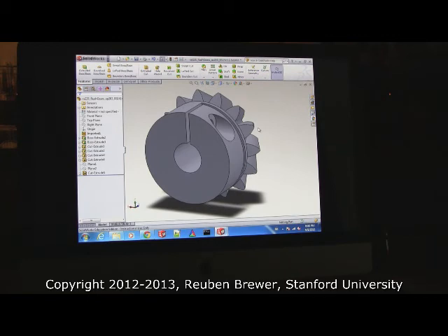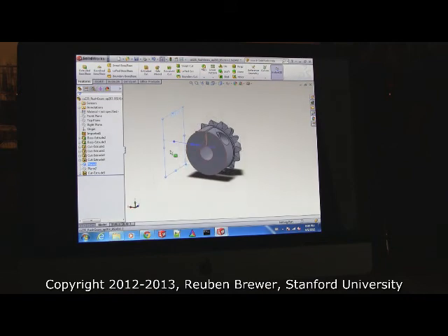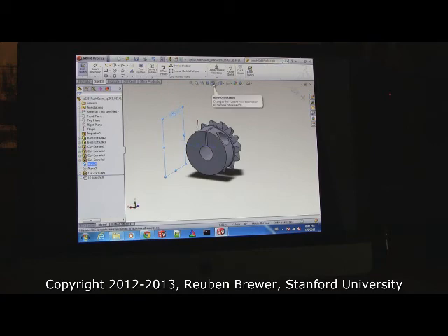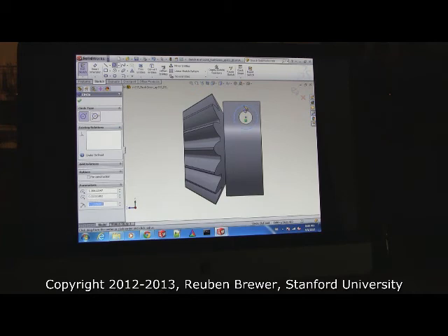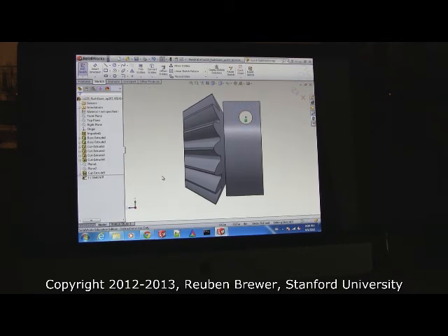Okay, hit the little check mark. Okay, this next one is fun. I think you actually really will like this. Select the other plane beneath the other hole. See this one? It's far away from the hole we just made. Select that one and do extruded cut. Now do the normal view. Okay. Now take a circle and center it here on that hole and make it about that size. And don't click; do for construction. This is reference only. Okay. Now hit escape. Now I'm going to wait and make sure everyone has this before I go ahead, because the next part is critical.